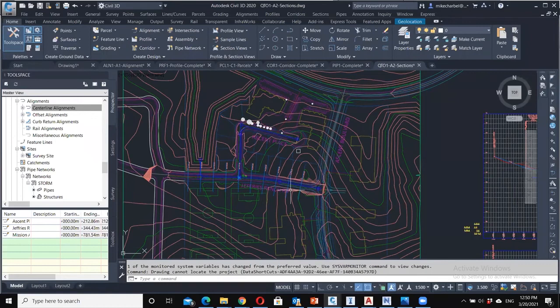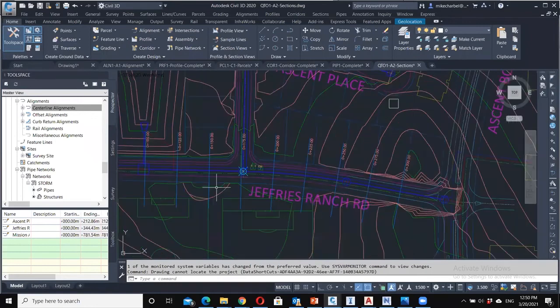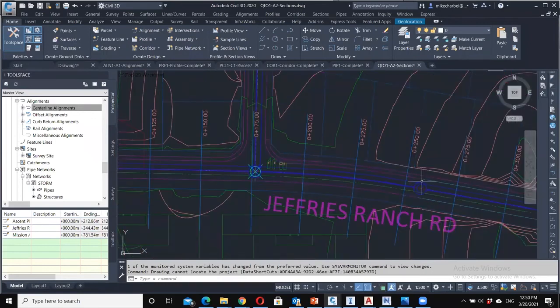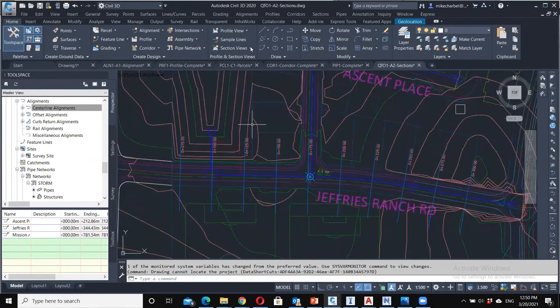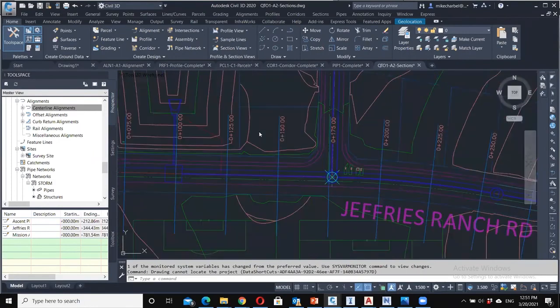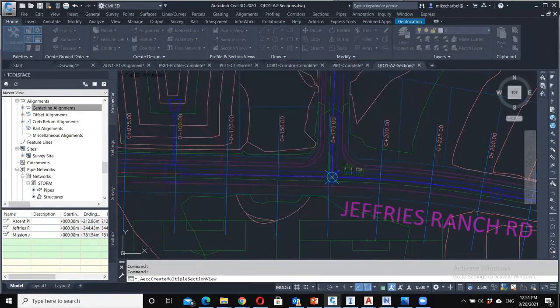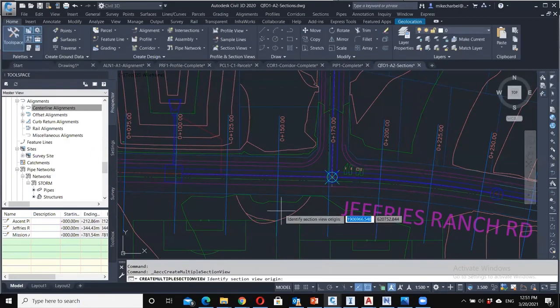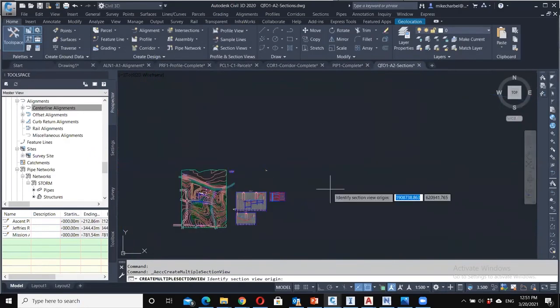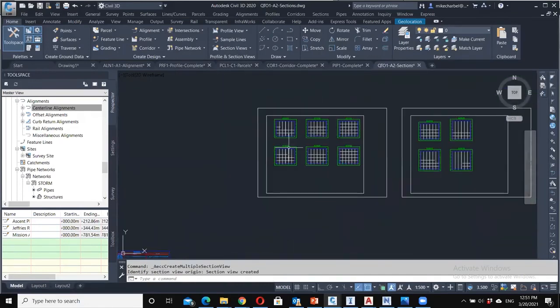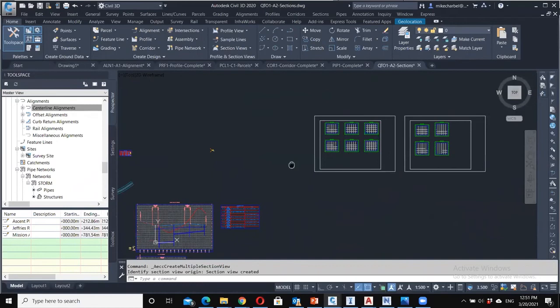Another vital option in Civil 3D is that we can form a sample line, and various sections, as I will do with a 25-meter distance between each. By clicking on Section Views, creating multiple views, and choosing my road alignment with this sample line that I designed to be right above it, then clicking next on Creating Section Views, we can now perceive this sample line's multiple sections.